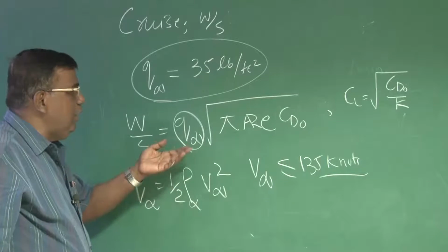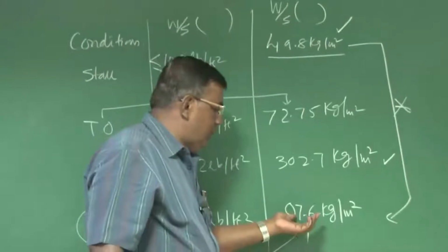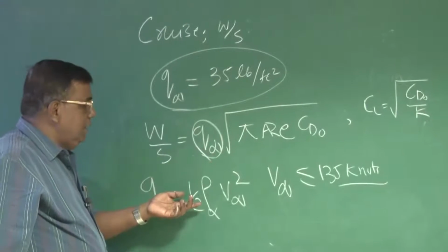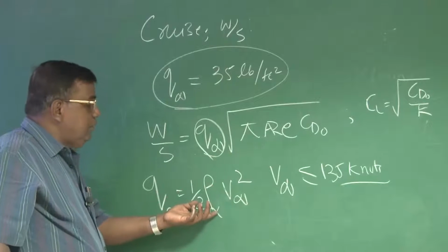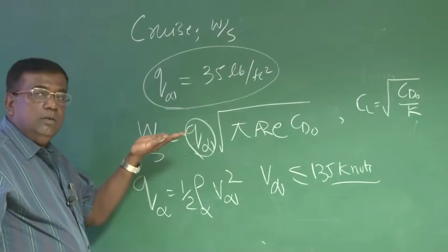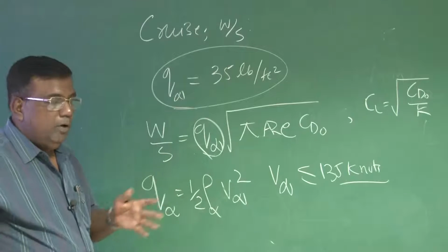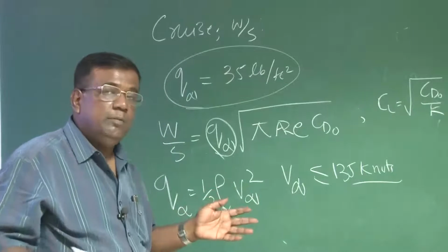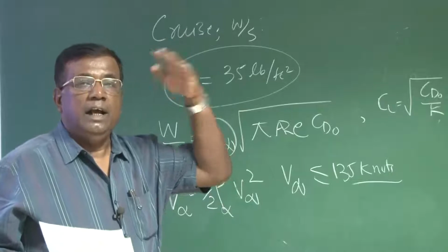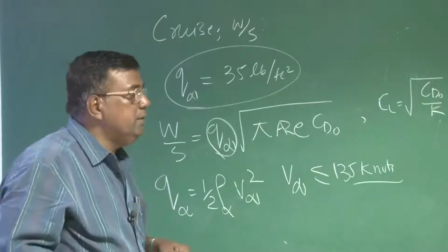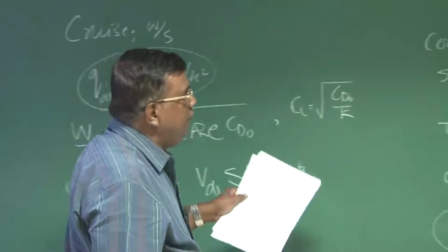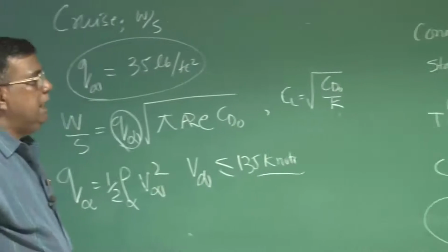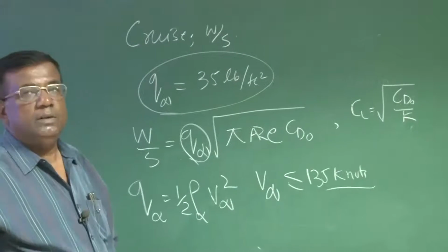And suppose it demands that you have to decrease from 97 to let's say 70, the option could be primarily you reduce Q infinity, keeping the speed the same. One option could be you go to a higher altitude, then it will reduce. But depending upon type of engine, type of navigation available, type of air traffic controller clearances for a generic aircraft of this type, much variation in the high end altitude will not be permitted. You cannot go beyond that. So all this sort of a conflict will come, and finally we'll have to pick one, and then we start calculating the mission performances with that.